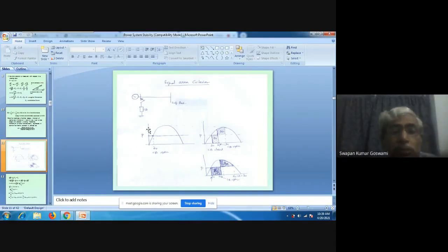Now let us consider a situation where we are using a circuit breaker here, as if to create a fault and to disconnect a fault, because we want to impose some disturbance and investigate what is the impact of that disturbance on the generator. This is our intention. That's why we are creating an artificial situation, where by switching on the circuit breaker, we initiate a fault here.